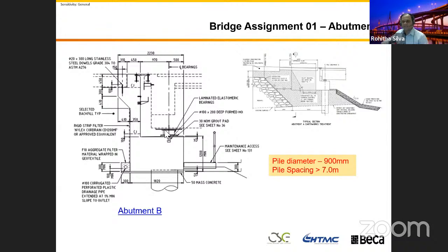Bearing is a flexible element designed for compression and shear deformation. Here, thickness will be governed by the shear deformation of the bearing. Area will be governed by the compressive stress in the bearing. It's very simple. The bearing compressive stress, if you remember, is limited to 10 MPa.